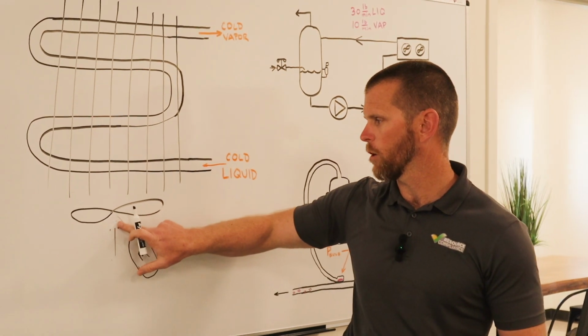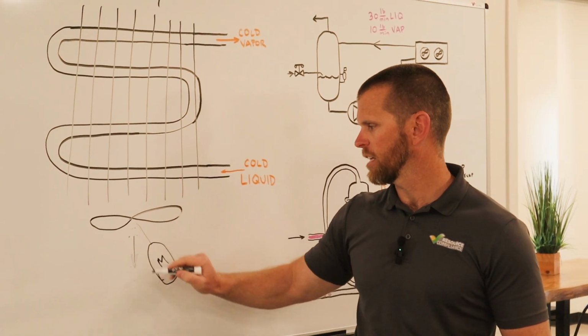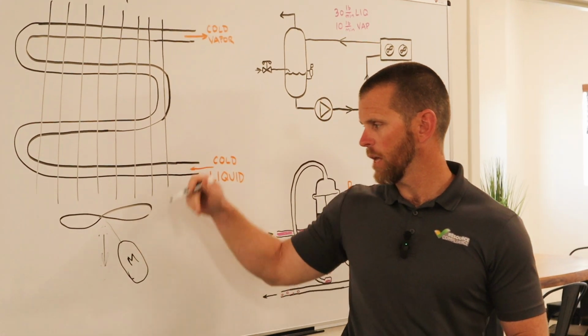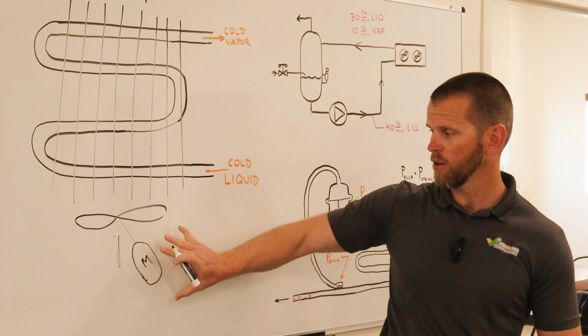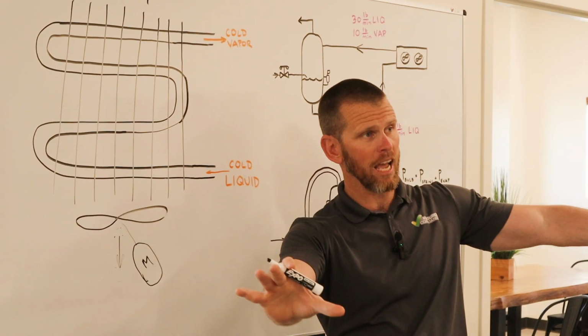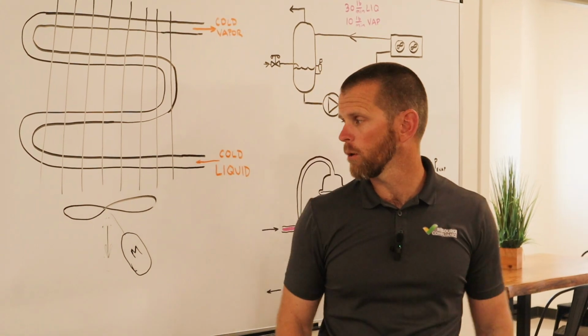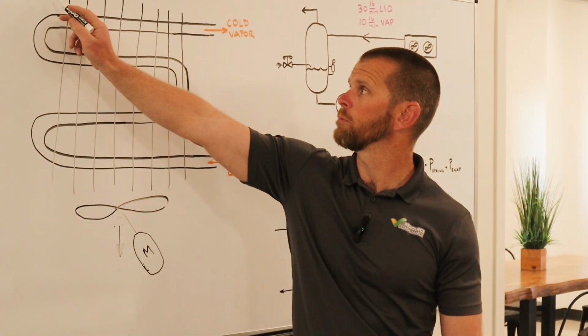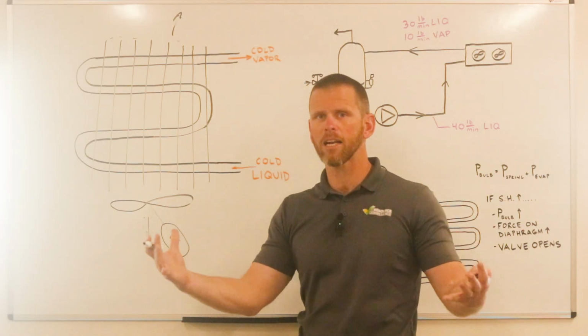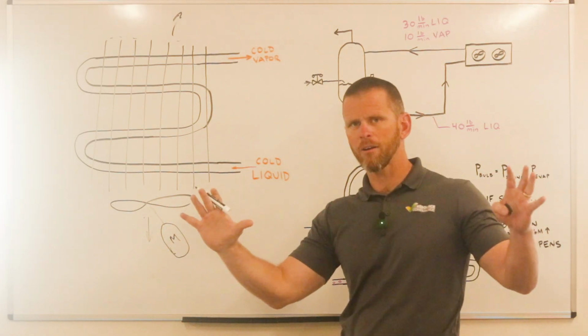So again, I'll flip my arrow back again as we show the air now getting pulled through. The downside here, that heat from the motor now is just getting broadcast into the room without first passing through the evaporator. But the plus side, we get a better distribution across the face of this coil, so more effective use of the entire area of the coil.